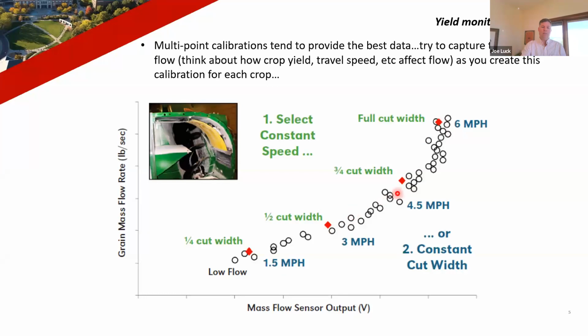It can be approximated between these for multi-point calibration, but that's been one of the big problems in the past, is that relationship has a bit of a curve when we're looking at actual mass flow through the system. So this is some of the data from the yield monitor test facility back then, where we could actually measure that versus the mass flow through the system. Our goal is, again, thinking about a lower flow through the machine.